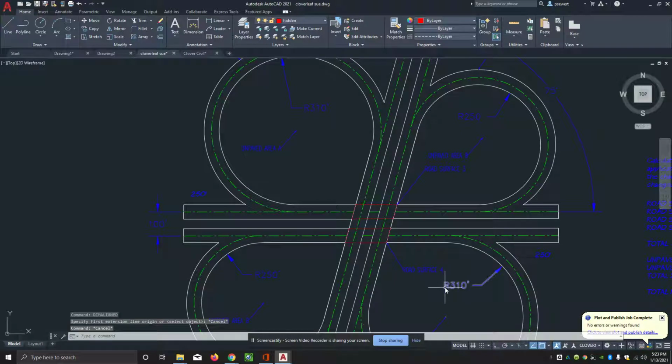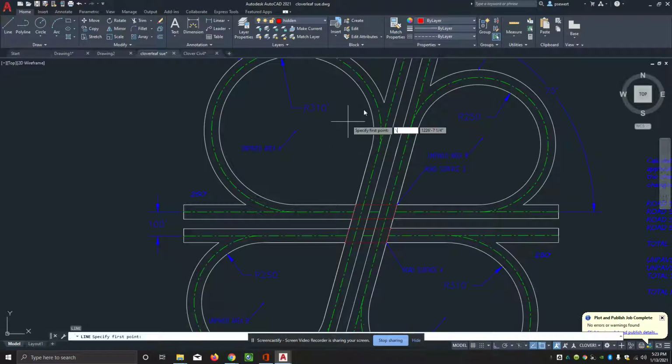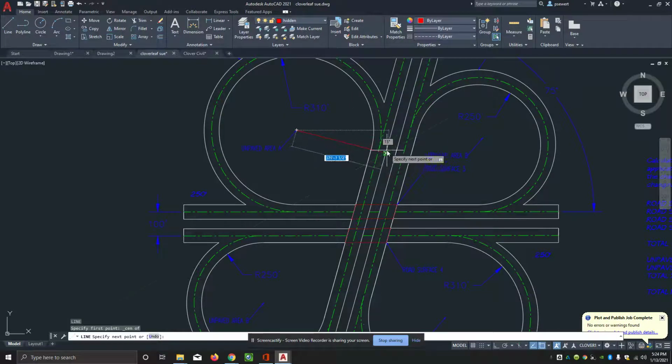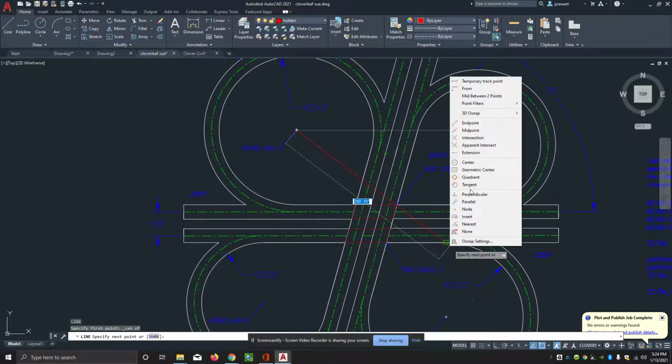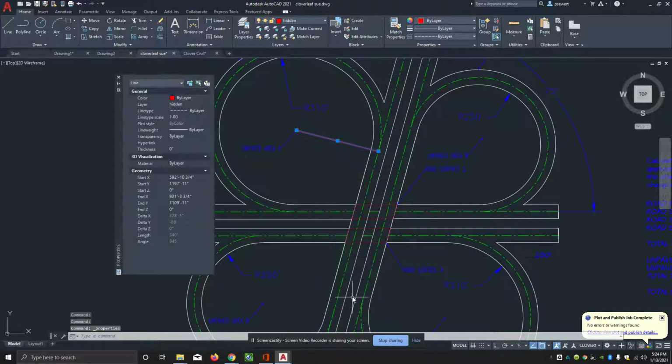Hold the shift key and right click. You'll get your O snaps if that's what you're looking for. Yep. That's like an override. I'm just going to issue an L command then. I highlighted that and I'm just doing a properties on that. You right clicked it. I right clicked it, yeah.